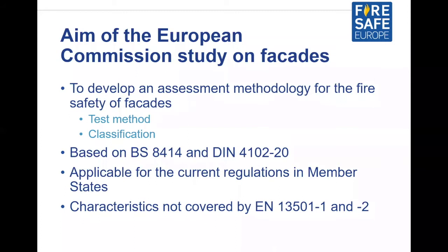If we start with the aim of this study, it was to develop a methodology for the fire safety of facades, and that was to include both a test method and a classification system. It was also supposed to be based on the British standard BS 8414 and the German standard DIN 4102-20.